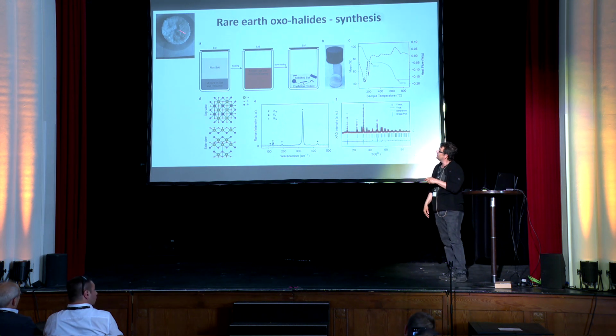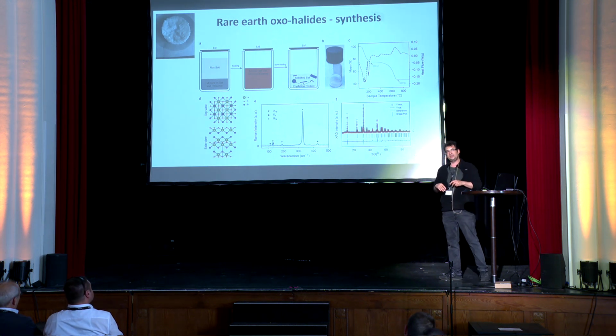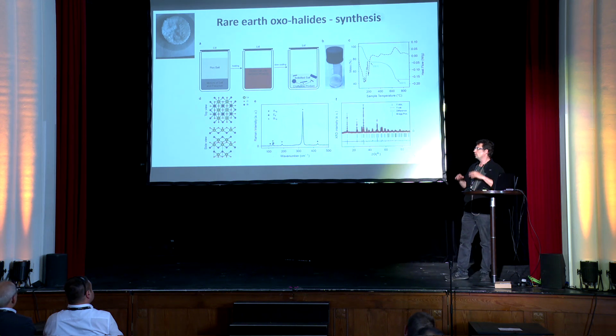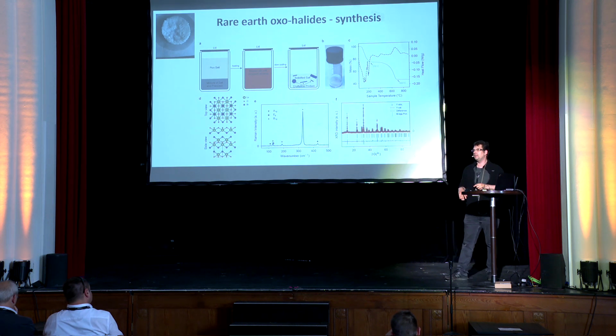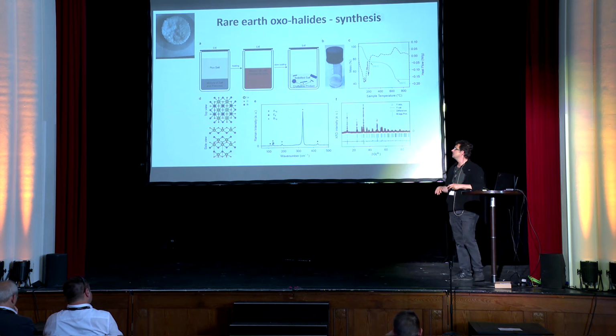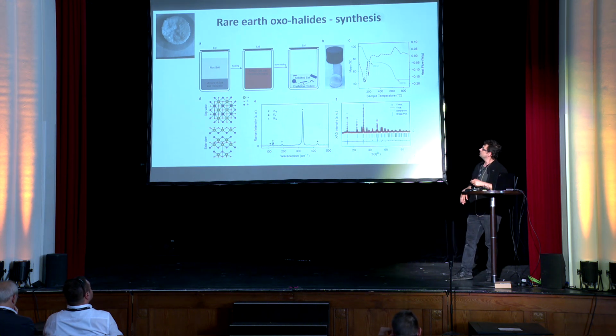It can be relatively easily upscaled using molten salt synthesis, where you react oxide or put in a hydrated compound, like we put there lanthanum chloride hexahydrate, and you just heat up in the molten salt system and cool down in air, and you get flakes in the millimeter size, which can then be used either for stamping or for ink fabrication.